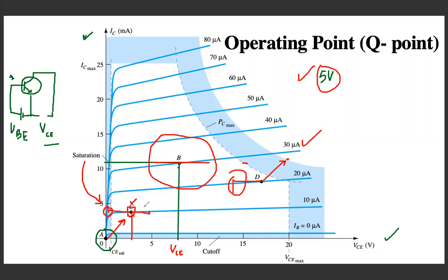Now similar to this point C, this will also work if we are using very small signal, very small values signal. ठीक है, so if we look at all this discussion, if we try to understand, it is that we want our operating point somewhere in the middle of the active region, and that way we can see that the relationship between different parameters is such that transistor will always be in the active region during all the values of the input signal, during the whole range of the input.